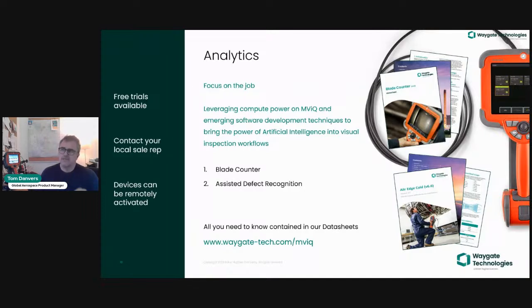What are analytics? Really, these are advanced algorithms that help you do your job. You do your visual inspection. What they really are is we've got two different types of analytics. We've got a blade counter, and we also have analytics that are designed to help you detect defects. We call that assisted defect recognition, ADR.